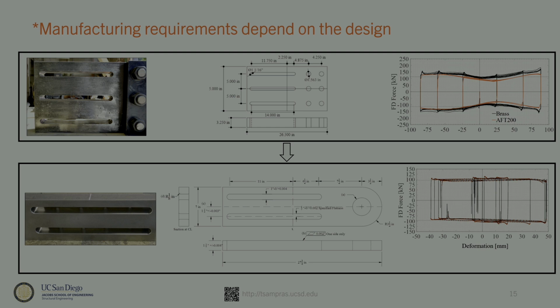On the right-hand side, you can see a force displacement behavior that's not actually Coulomb-type friction because you get some strengthening, I guess, with respect to the displacement. So your force is basically coupled to the displacement. This is because on these components, we have no tolerancing for the machining of the parts in this connection. So there was an imperfection in the parallelism of the slots. You can imagine when the bolt was sliding in the slot, it was coming and bearing against the slot, and there was an additional friction force that was secondary but significant for this force level.